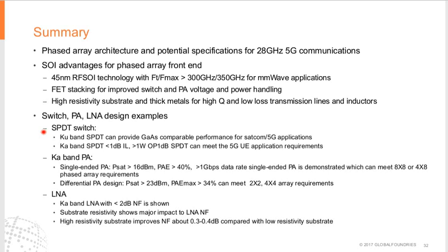This is a three-stack SPDT design. The 0.1 dB compression point is about 25 dBm, and also the soft breakdown. So it will have a 2 dB margin for this application.